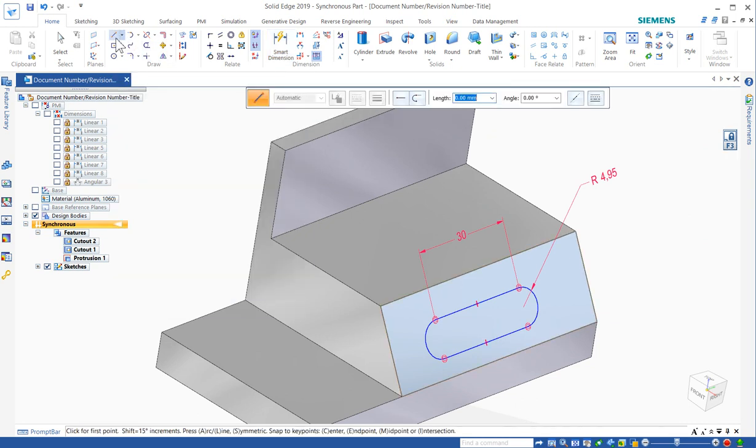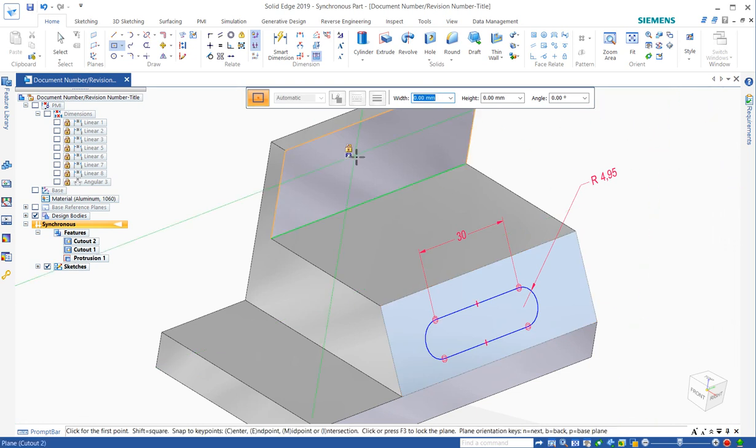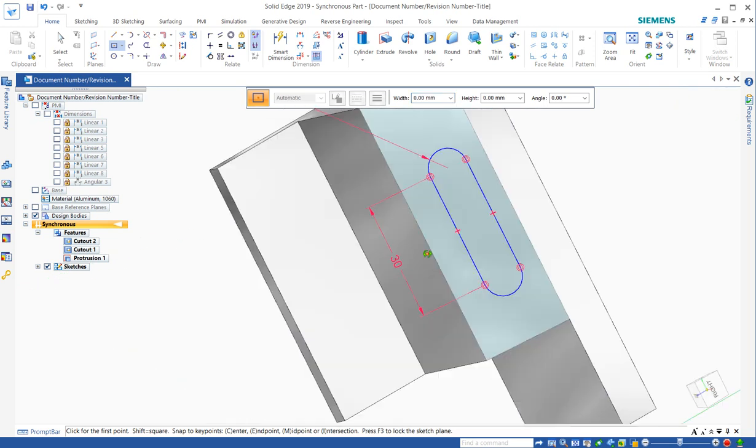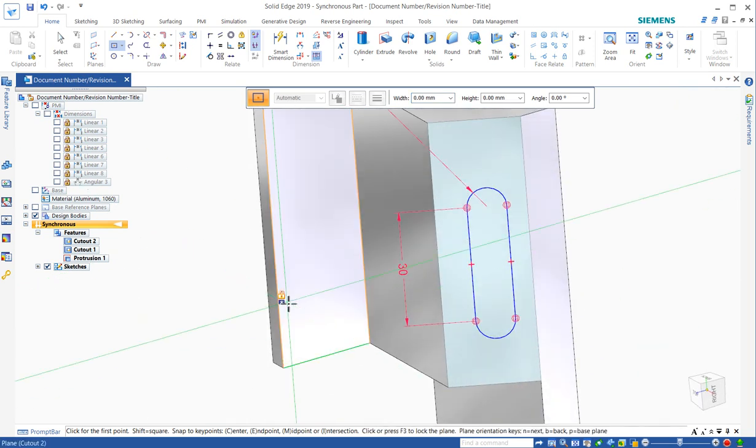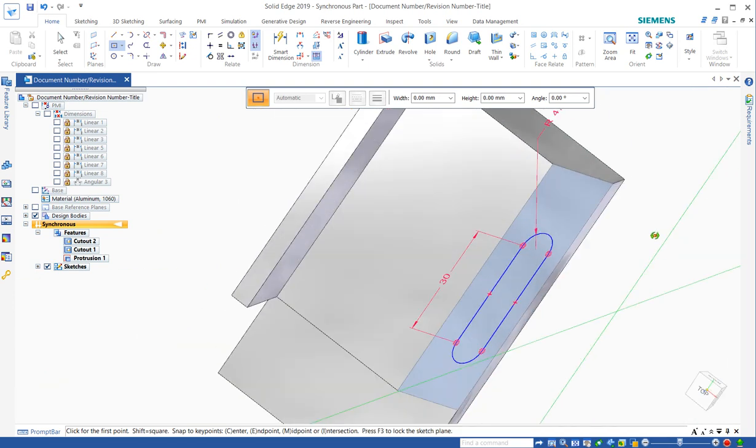So when you start a sketching command, so I start the rectangle command, now I'm previously locked to that face, and that might throw you for a second. If you click that button to release the lock, you can now hover over a different face, and the software will usually find the face that is the most horizontal. So you see it's finding that.